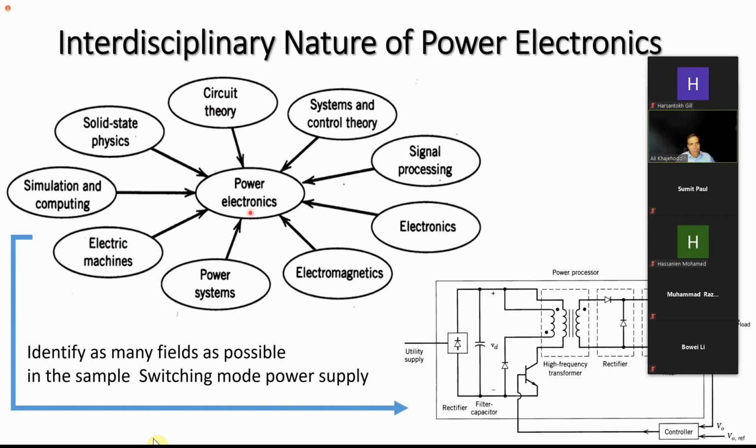So we can do whatever we have in the first step to design it, but then you have to simulate it with ANSYS or some finite element method simulation software to actually understand exactly how these magnetic fields are going inside, how this whole thing is interacting, how the switching actions are happening and losses are formed. And these things become very complicated and very important.